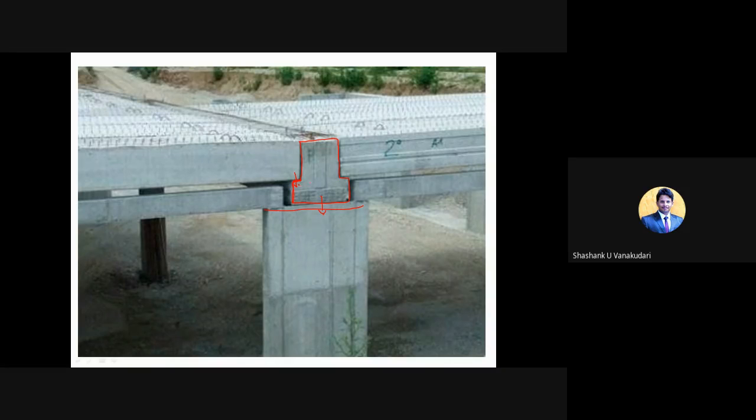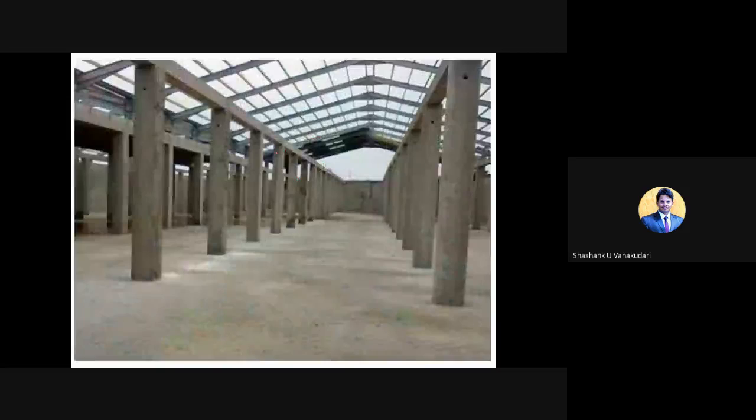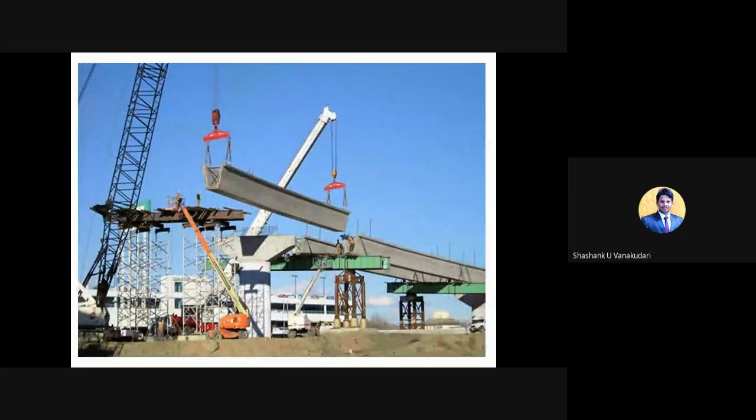Okay, so these inverted T beams are also helpful in the joining of slabs and beam connections, and the gaps can be filled by some sealants or adhesive materials. Clear? When you require more load carrying capacity, you need to prefer these types of inverted T beam sections. Okay, and you can also see the rectangular members here.